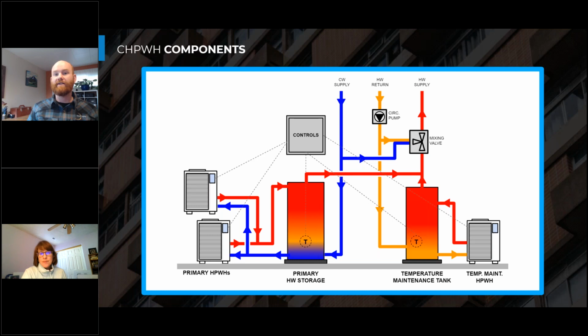So there's great potential there, but we need some relay with the utility to understand when we should be doing that or when we should be not heating our water. So that's what the CTA 2045 port does, it's a communication port between the heat pump water heater equipment or the system and the utility, so that we can load shift, load shed to really make best use of the electrical energy on our grid at a given time.